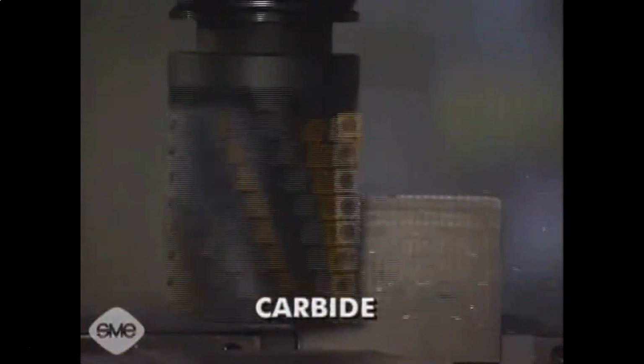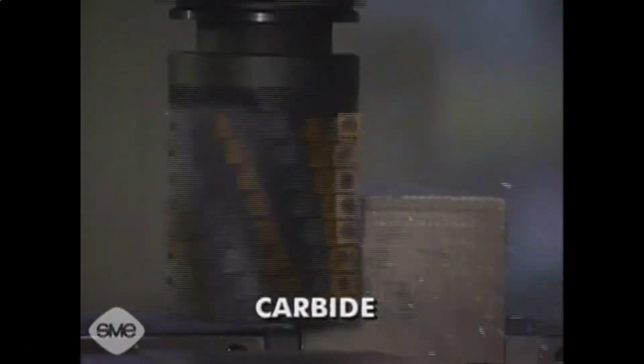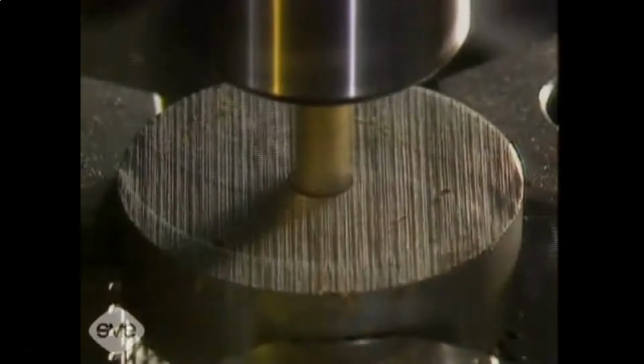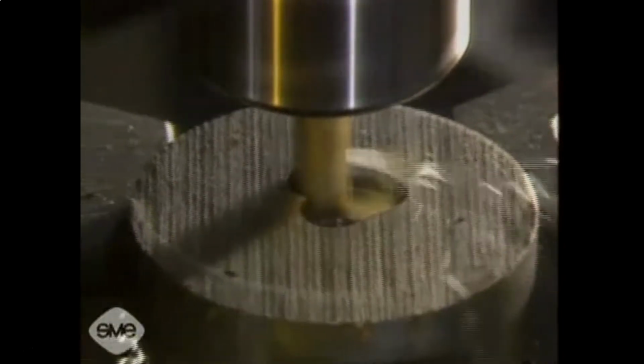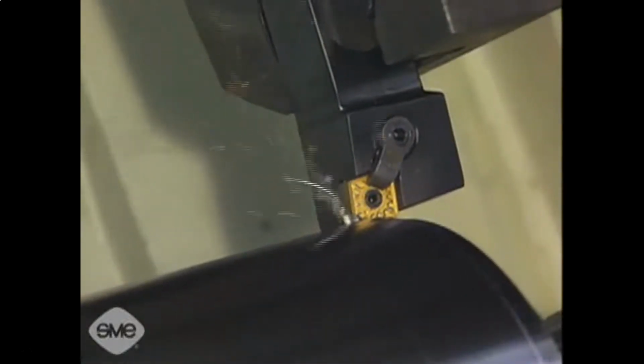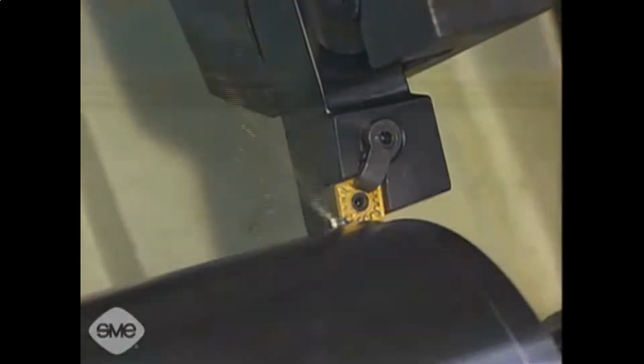Carbide tools, particularly coated carbides, are today's most common cutting tool material. There are a great variety of carbide compositions and coating types. Carbide tools may be indexable inserts, or solid round tools such as small diameter end mills or drills. Coated carbide inserts are the first tool material to consider for most production operations. Most insert coatings have multiple layers to protect the tool against abrasion and chemical wear.